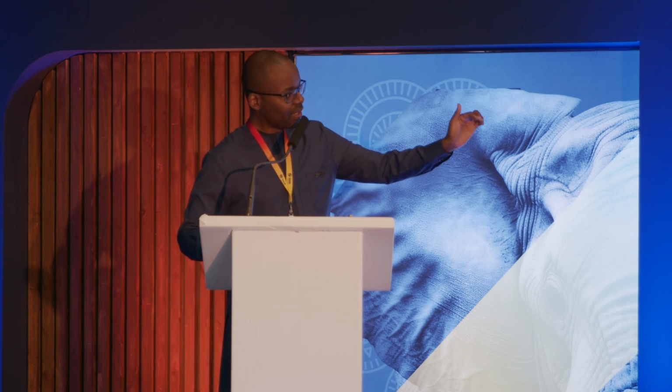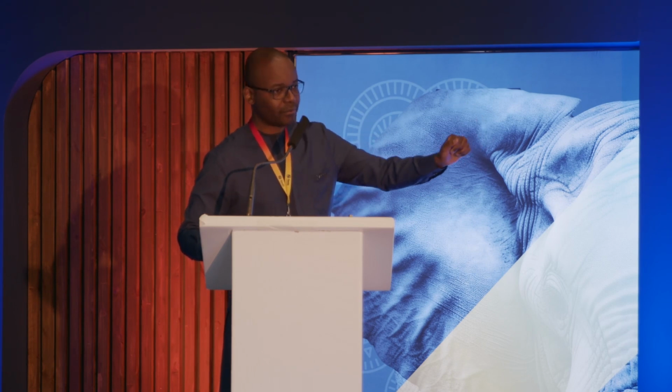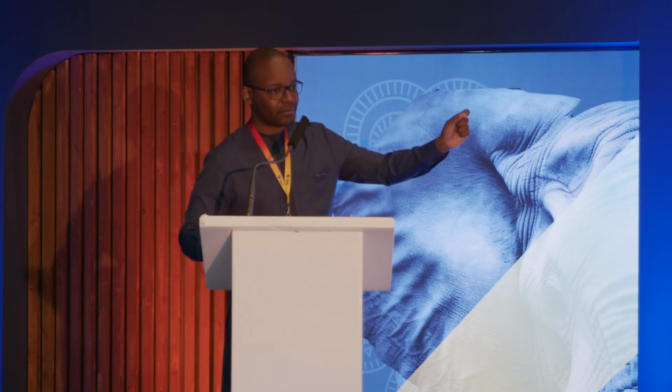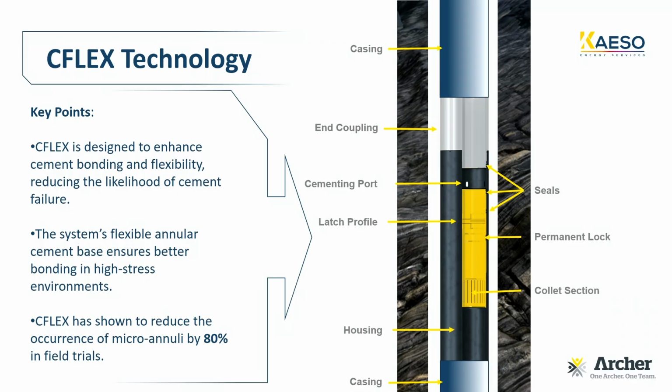And what the CFLEX allows you to do, you see that you have a cement port, and that cement port allows you to get in contact with the annulus. So it is through this port that we can squeeze the cement to place it exactly where we want to.